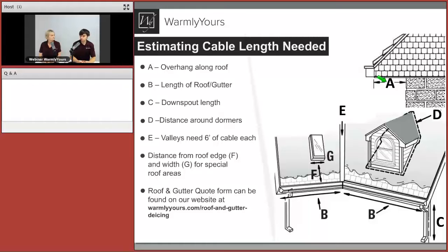We actually had a question from Karen about this exact measurement. Karen asked how to prevent ice dams from forming on a roof with a 2-foot soffit or overhang. That's the same measurement that we're trying to use. A 2-foot soffit would not present a problem for us, because we have design guidelines that account for it. As soon as we know it's a 2-foot, we would specify the correct multiplier, add more cable on the zigzag patterns, and cover the overhang in the correct manner.